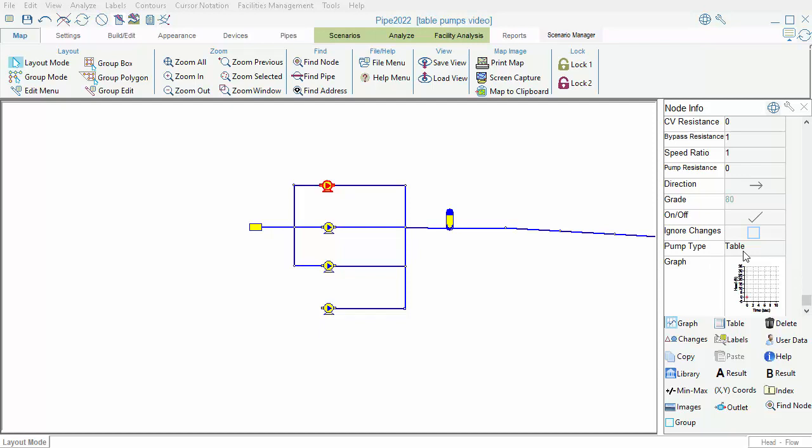If you want to model a pump trip where the pump loses power and runs down under its own inertia, then a file type pump or a file table type pump is required. Setting up a pump shutdown, a pump startup, and a pump trip will be discussed in a later video, and we will also discuss file type pumps for surge in another video.